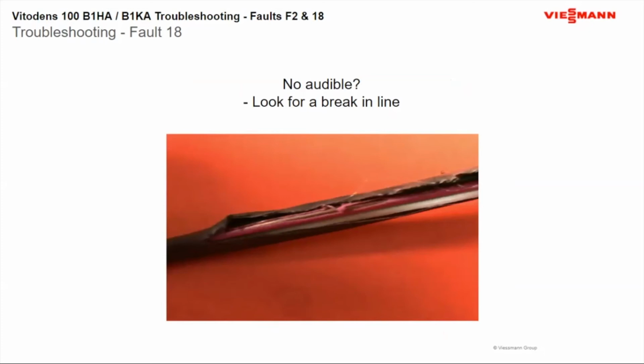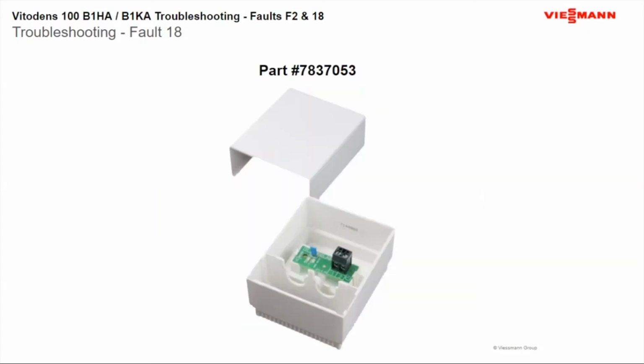And just remember, with this boiler, if you don't have the time to troubleshoot it, you can power it on and off, go into coding, take your outdoor temperature sensor out, and then just let it run to whatever temperature you want. If you're running high temperature, you're going to put a fixed set point to your max temperature of 180, or 179 in this case. That way, when you get time to go back, if it's in the middle of winter or whatnot, you can go back and fix the wire. If you do have to change the sensor, there's your part number there.